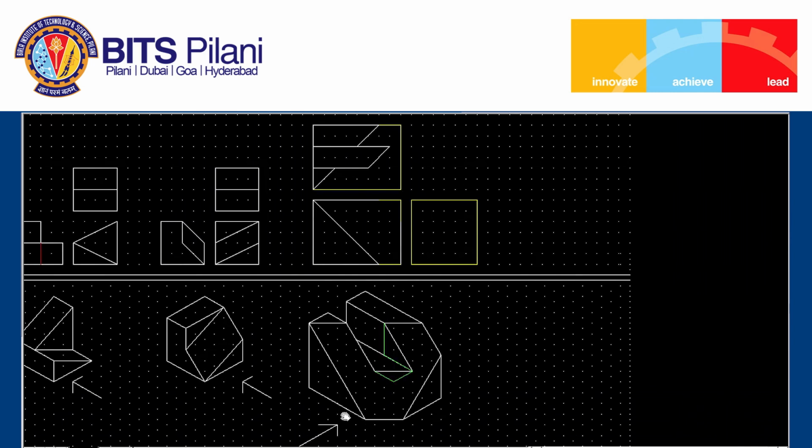Now we will join the corners for this Q surface. This corner appears here, this corner will appear here, this corner appears here, afterwards this corner will appear here, afterwards for this corner 3 grid space along the height and 3 grid space along the length we have to move, then we will obtain this corner. Similar way, this corner depth dimension will not be seen in the front view, and along the length you have to go 2 grid space. Then this corner will appear here, this corner will appear here, and that particular surface will be satisfied.